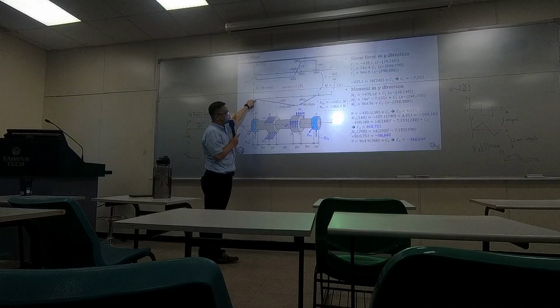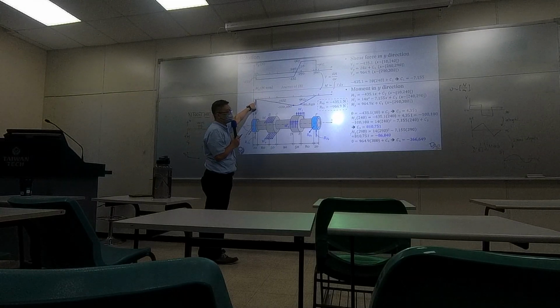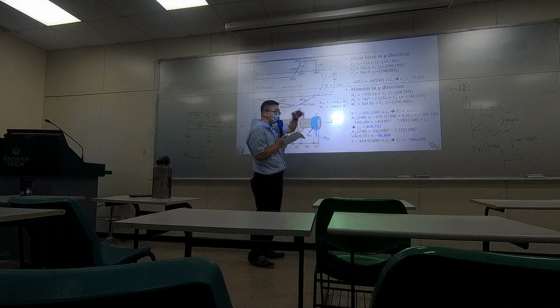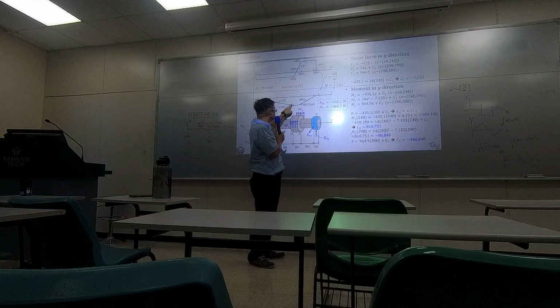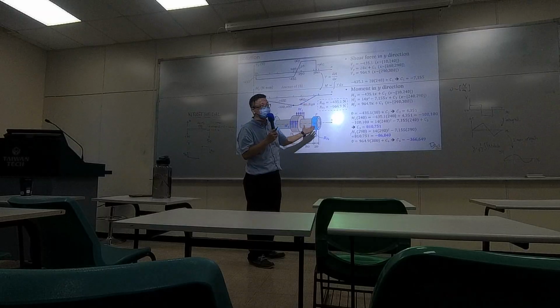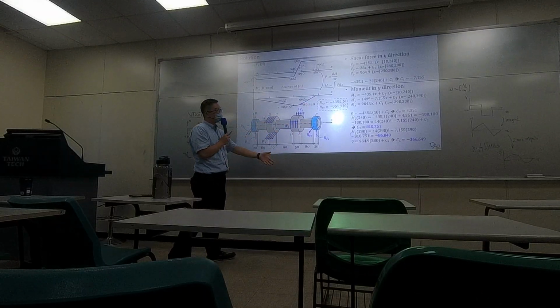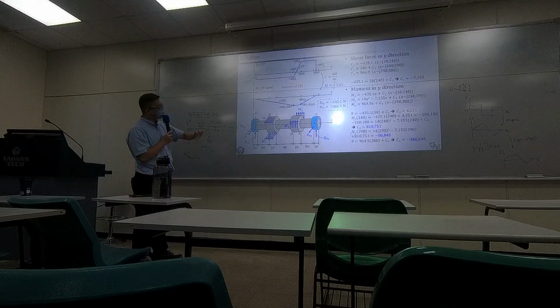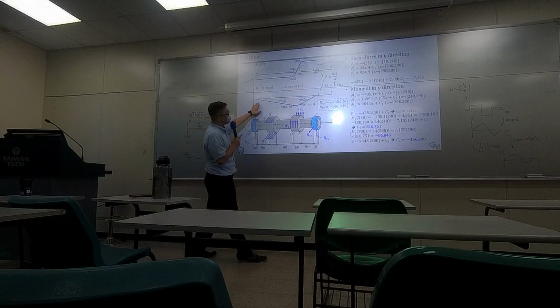So that would be one position that you can use. And also at the edge, usually the moment is continuous, so the value on both sides should be the same. So using some of the boundary conditions, you can determine all the values you need. Then you make the drawing.